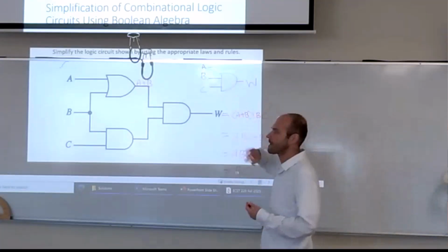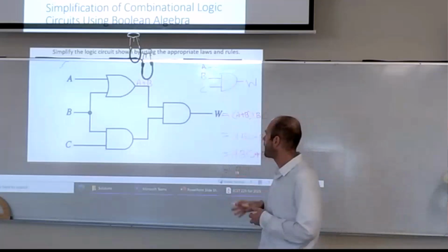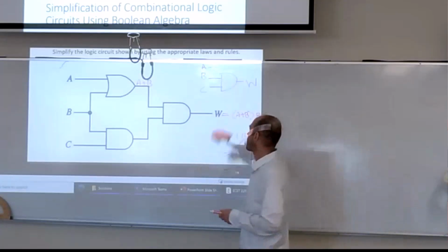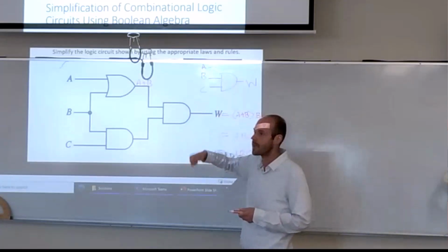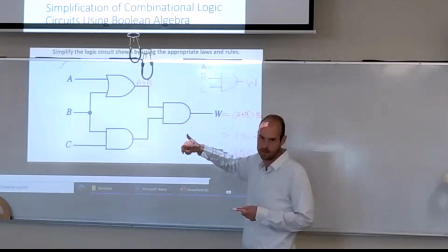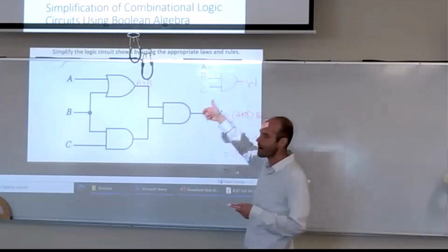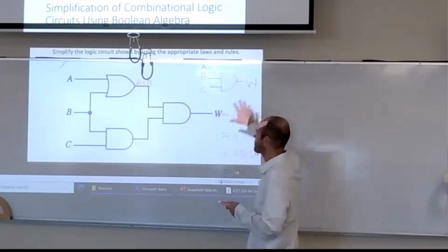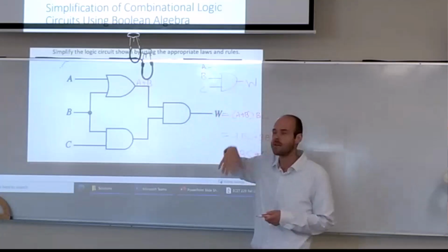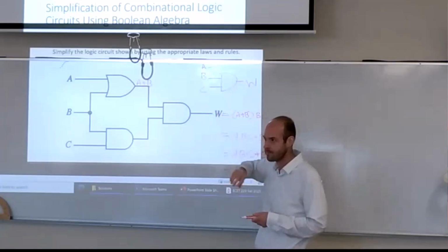What that would mean is if you looked at the truth table, you could go to that truth table and flip A on and off, and it would not impact the output. So A is an entirely redundant control in this particular case. It does not impact the output ultimately.